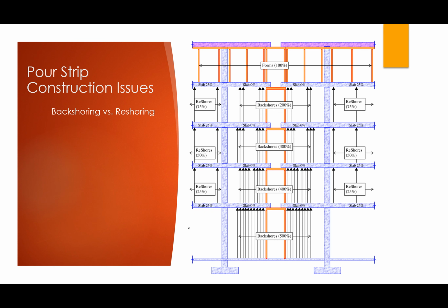And think about what we said early on with these pour strips. You want these to be open for an extended period of time, right? Something like maybe 8 weeks. Somewhere in that ballpark. 60 days is ideal. Now, contractors generally can pour, sometimes 1 floor per week.